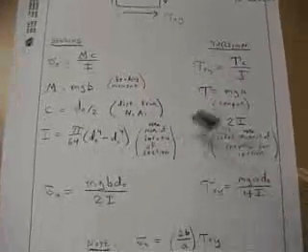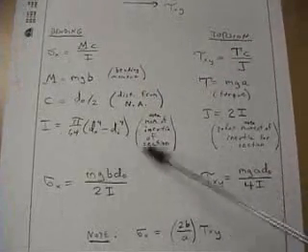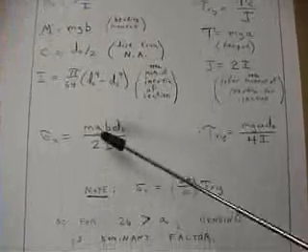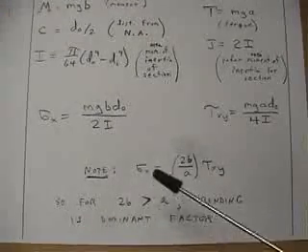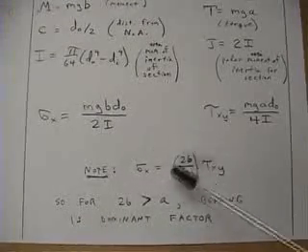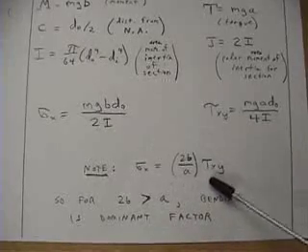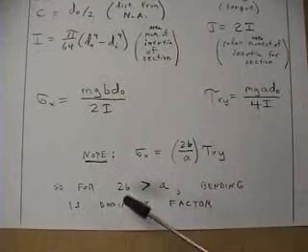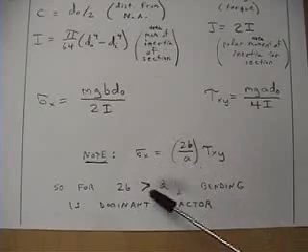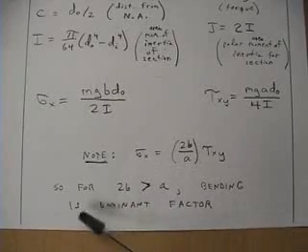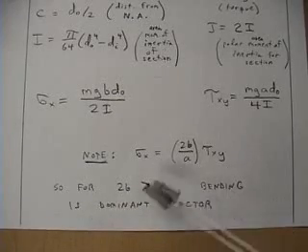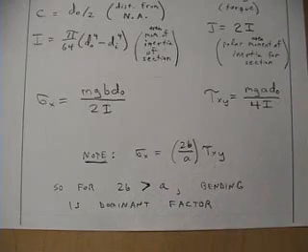And when we work through all the details for the tube cross-section, we get expressions for each of these stresses, and we can see that the bending stress is this factor times the torsional stress. And for our experiment, 2b is much larger than a, so bending is going to be the dominant factor in terms of stress being experienced by the rosette.